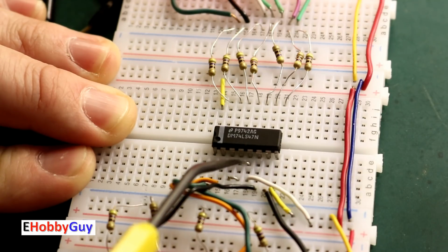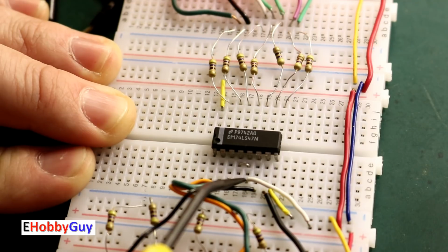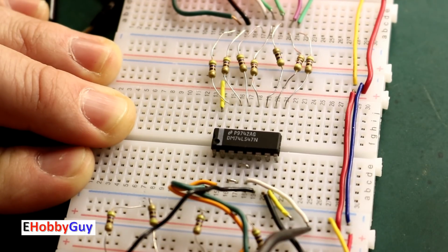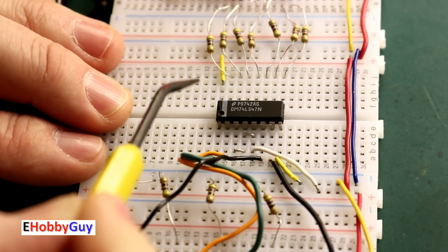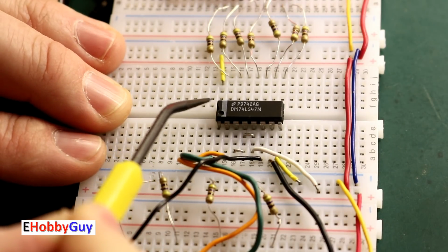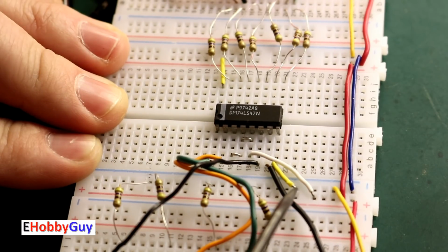So all 3 of these pins are tied together, and right here I have a jumper going from any one of these 3. I'm pulling them high right here. Now jumping to the other 2 things, which are the simplest of all. VCC is to pin number 16 right here. Pin 8 is being pulled to ground here.